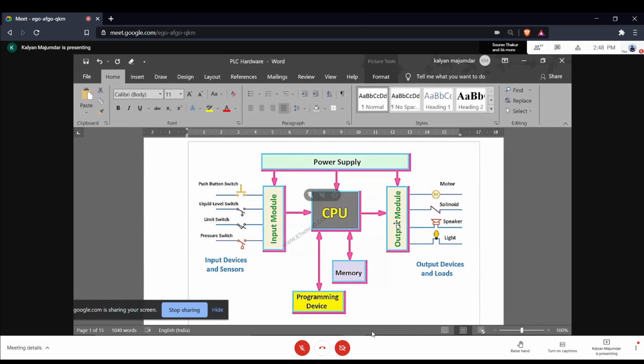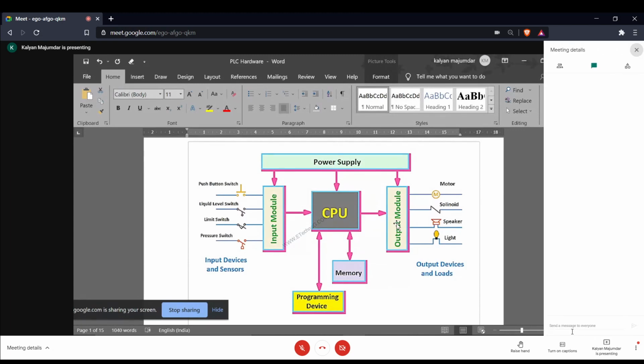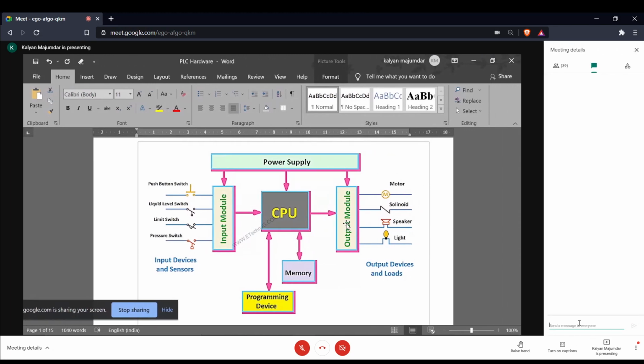The programming device is connected to this interface. Here it's got an RJ45 connector. Your desktop computer has got an RJ45 connector. As of today, a PLC is also provided with an Ethernet interface as a standard option. So that Ethernet interface on the PLC and the Ethernet interface on your laptop or desktop establish a connection between your programmer and your PLC, and then you can write a program, download it to the PLC, and see a program executing in real time.